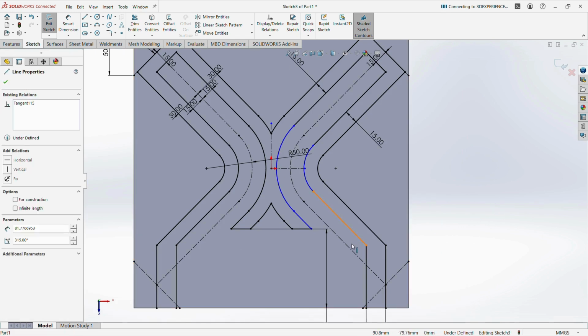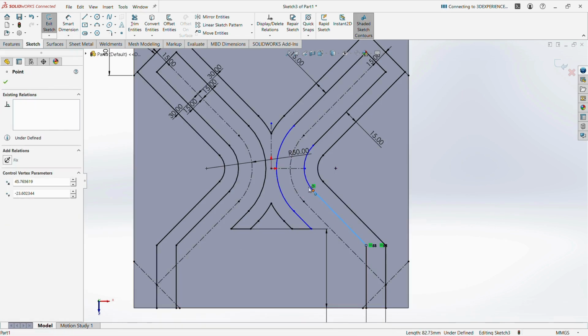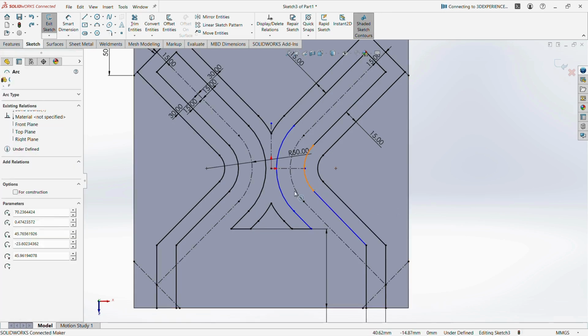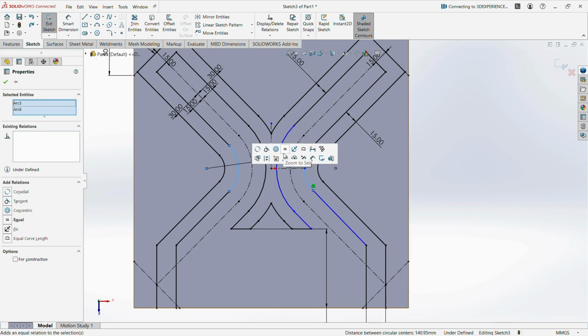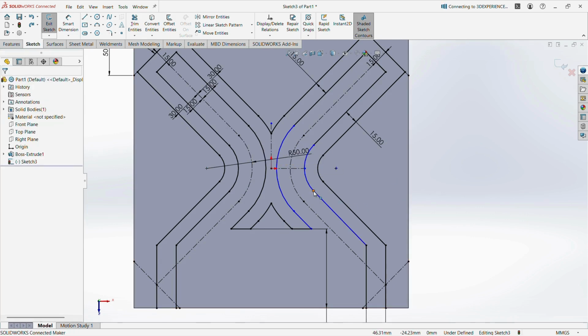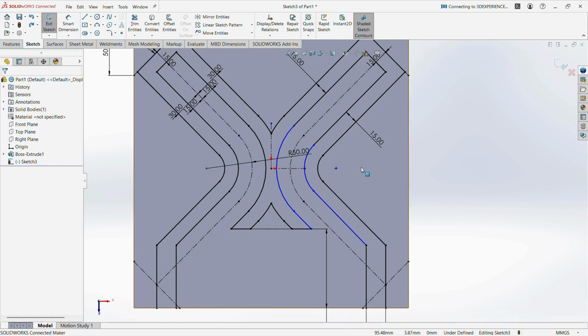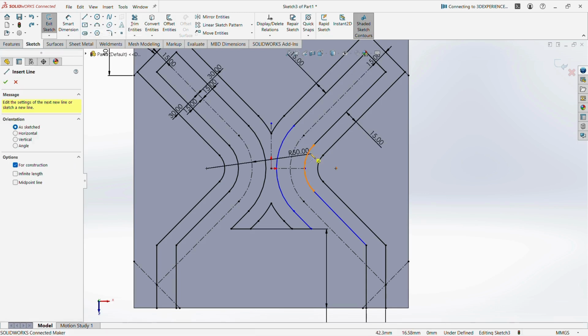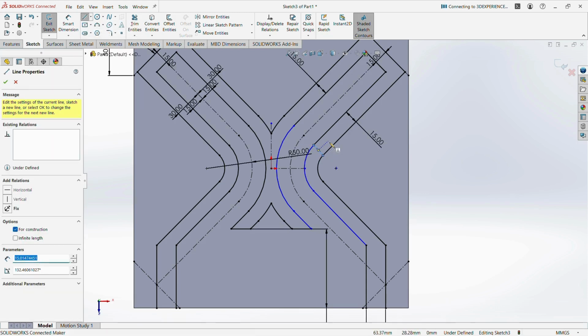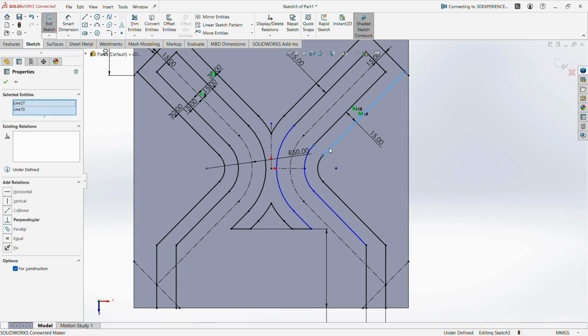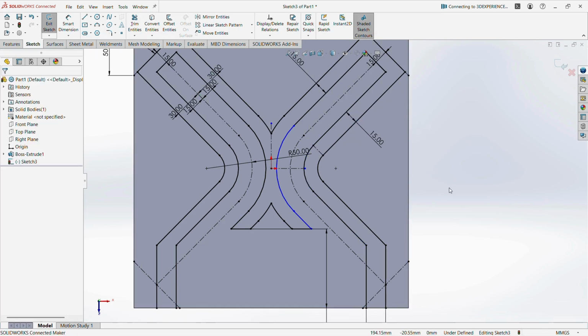Here we are going to apply a geometrical constraint because the numerical value is not working in these positions. It creates a new kind of error in this area. So we just eliminated it and initiate new constraints one by one. Almost selecting this line profile, then mention the parallel constraint. I am going to connect the two opposite points and fix it with this perpendicular constraint.